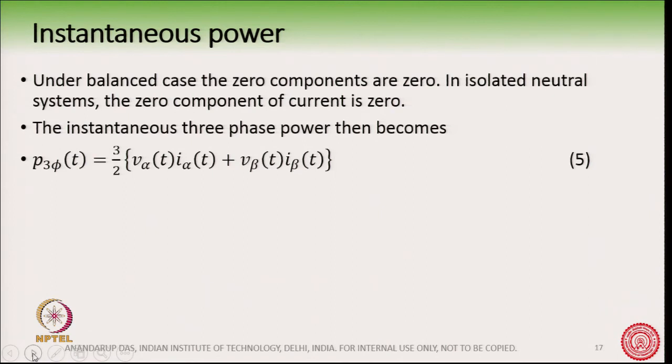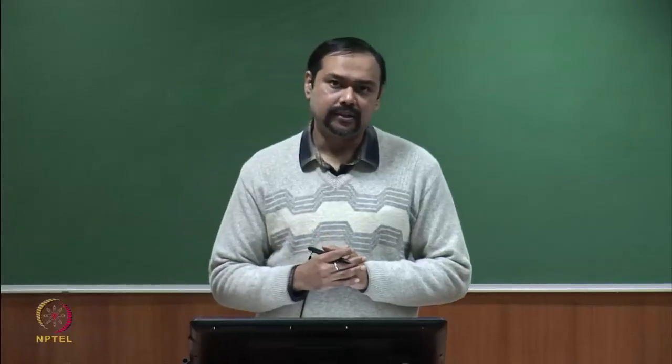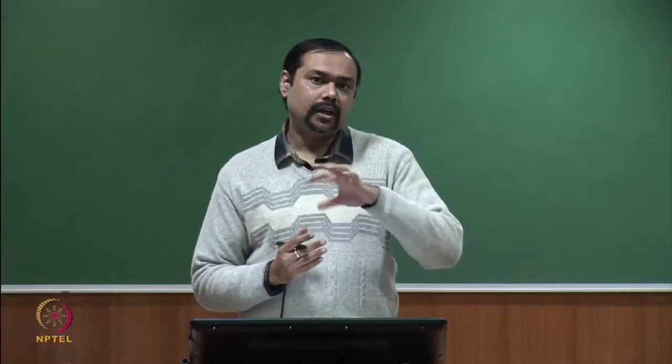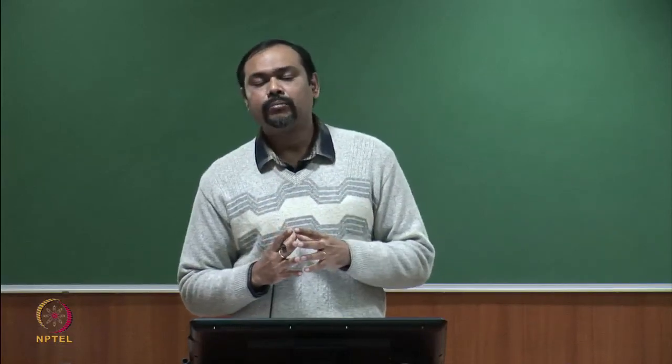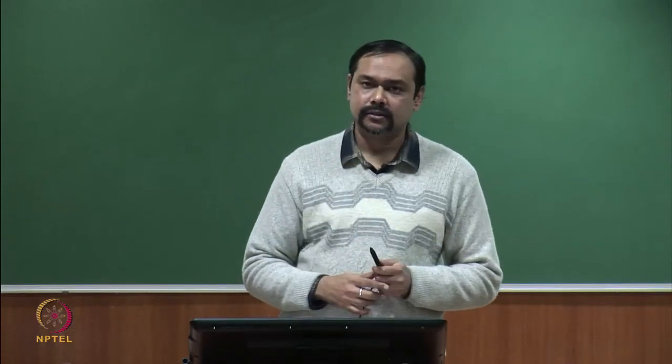So, when we are dealing with power, we do not need to take care of that 0. Now, earlier we had talked about a 0 sequence component or a 0 component in the space vector, and when we did the space vector PWM, if you remember, we deliberately introduced a 0 component, a common mode component in the 3 phases in the voltage.